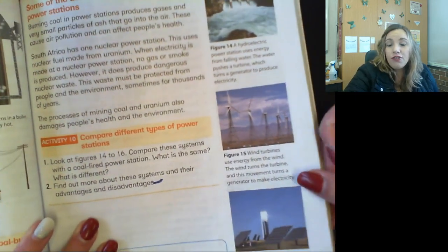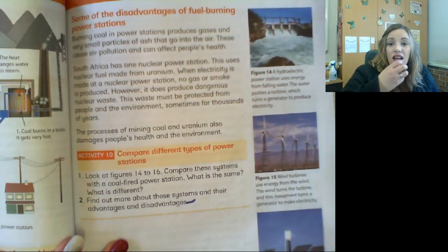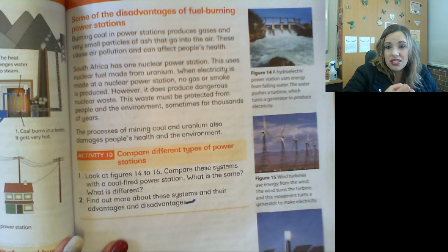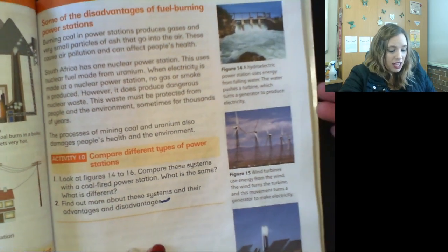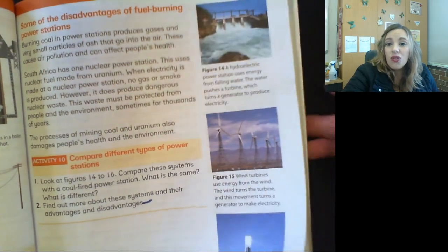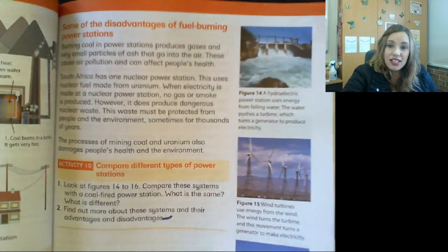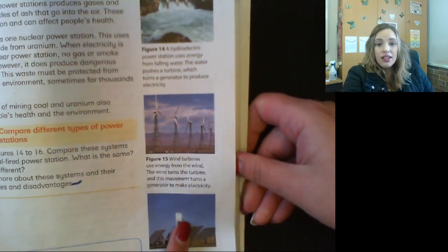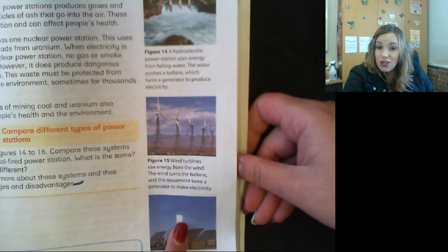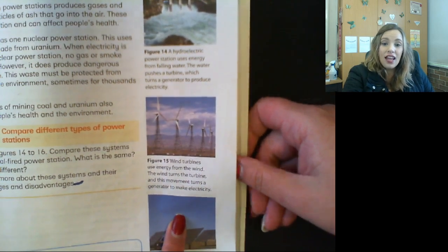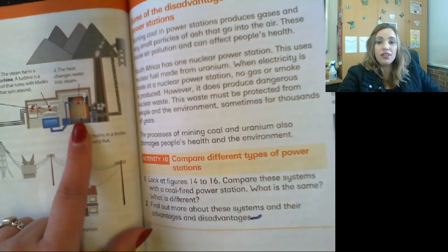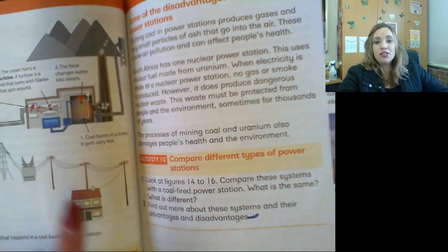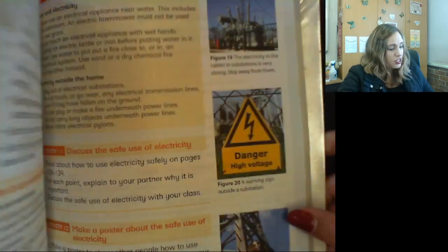One is a photovoltaic cell, meaning the solar panel itself changes the energy from the sun into electricity, and then another one where they use solar panels or mirrors to reflect the heat onto a specific point where they melt a substance, which is actually salt, molten salt, and that then acts similar to the boiler. It boils water, that creates steam, the steam turns the turbine connected to the generator.